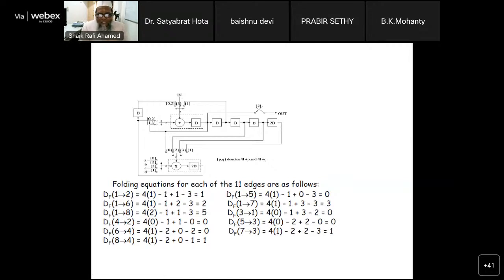So this is one part of this presentation, but all this requires multipliers. Multipliers I am going to discuss in the coming slides. A multiplier is a computationally intensive operation which requires a lot of gates. There are some realizations which do not use multipliers, which are called multiplier-less architectures. We have quadratic based and DA based architectures. I will discuss the multiplier-less architectures after a break of 10 minutes.